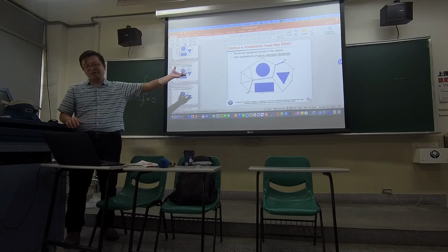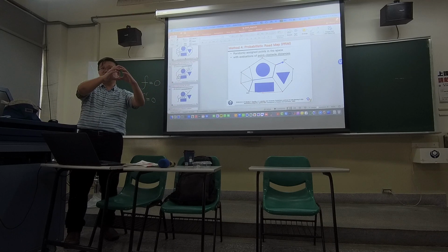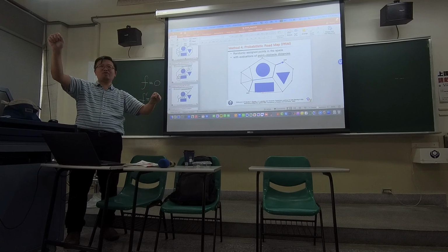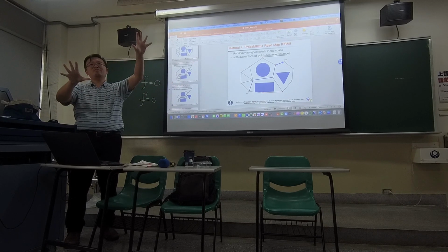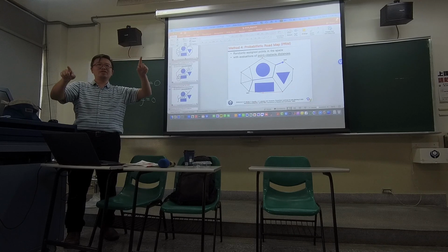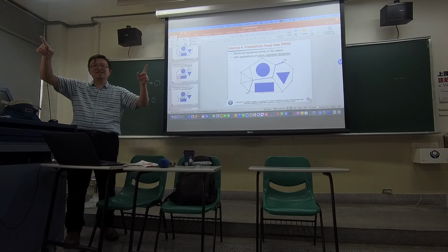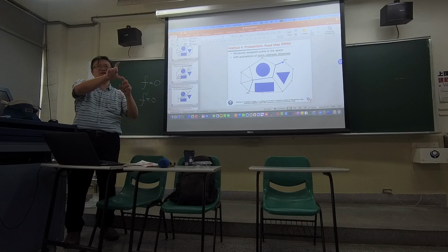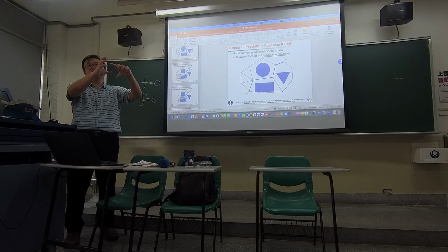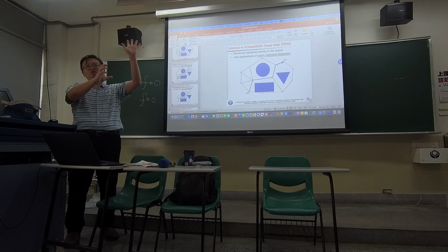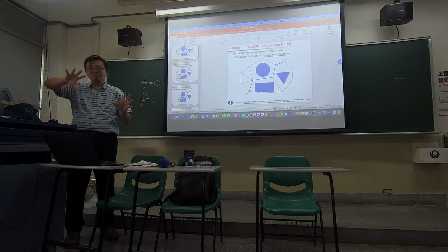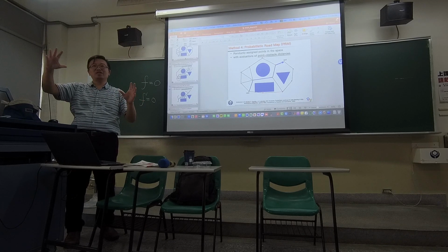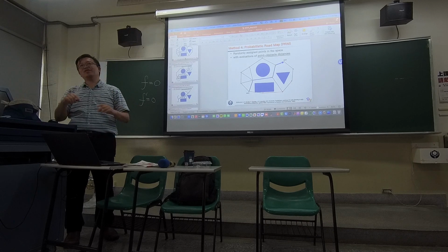If you do something like this: a random circle, random starting and end point, put in some random intermediate points, start to connect lines, and check each line whether the line is overlapping with the circle. If it is, remove those. So at the end, you will end up with a network without collision. Pick up the shortest path.